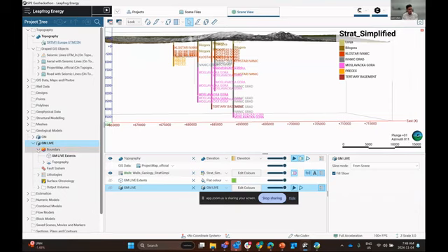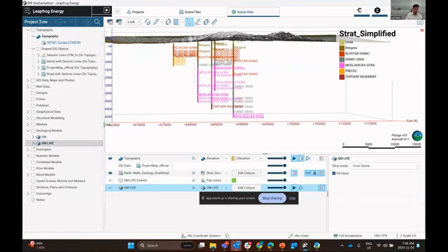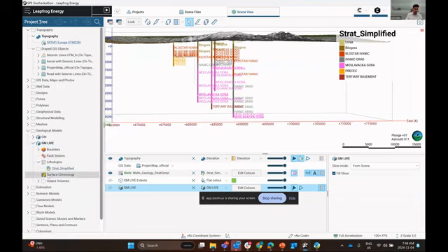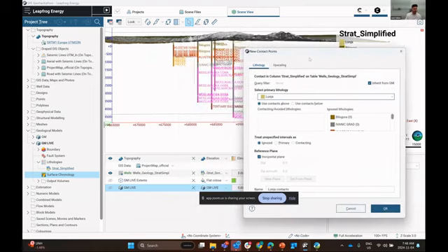Perfect. All right, so I'll actually take you through the process of constructing some of these surfaces and activating them. If we right-click Surface Chronology, we can create a new deposit or new erosion. In this case, I'm going to create an erosion surface from base lithology. So just to repeat, expand out your geologic model, right-click Surface Chronology, and press New Erosion from base lithology.